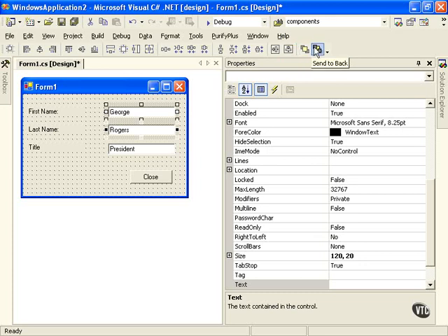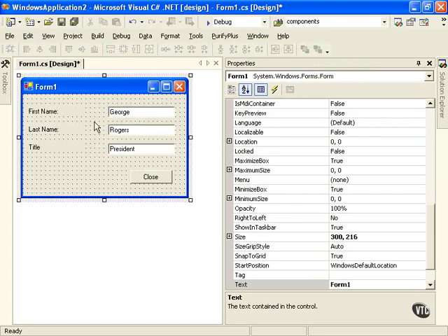And since everything is going to be on a particular form, they can overlap, so you can bring them to front and send them to back. This is going to be used quite a lot, as well as adding buttons if you wanted to. This is going to be used quite a lot for you when you're moving things around. You can multi-select, and then use your arrow keys to move things around. Be careful with the shift arrow key, because that's going to